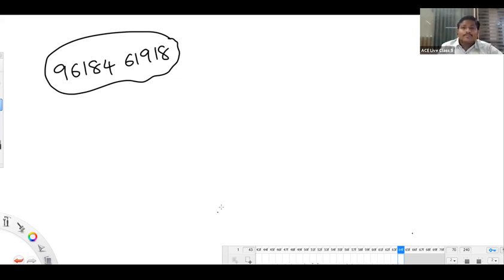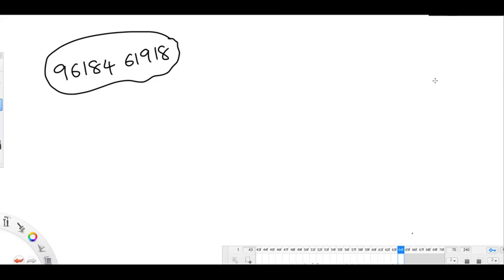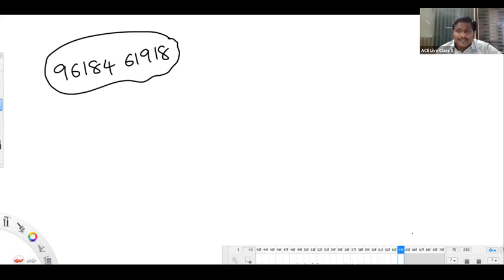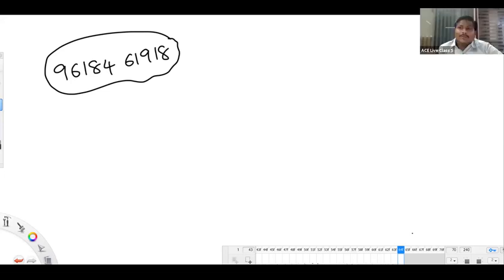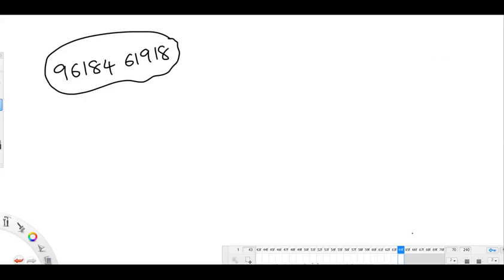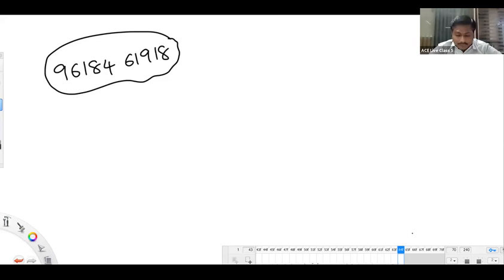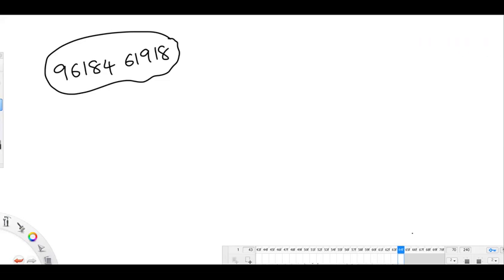Pranjali. Hello, sir. Tell me, Pranjali. Sir, in that guard wire we are using, one side is connected to the conductor and the other side is free, right? Yes. So sir, if we connect that other side also using some insulator or something, then we can keep it, or it's useless, right? It's useless. Again, you are connecting the insulator means that cost you have to spend, and who has to bear the weight of insulator? Tower has to bear it. Yes, sir. Again, that insulator will have a low efficiency again. Some issues will be there. Yes or no? Yes, sir. Okay, sir. Thank you.